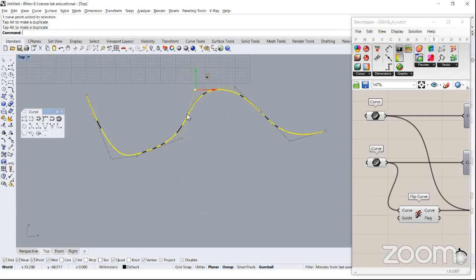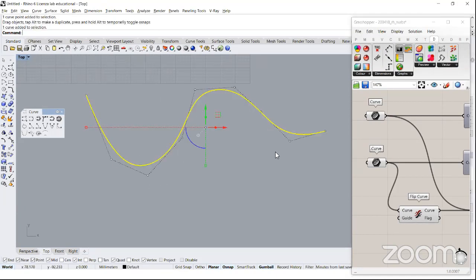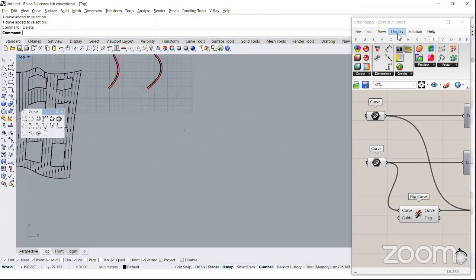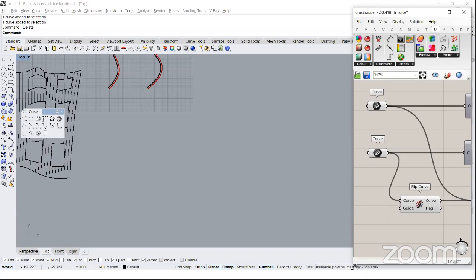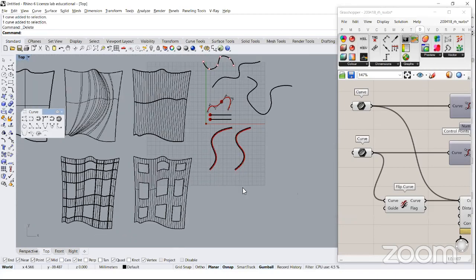So once again, topology, guys, if you know how to deal with topology, you can decide exactly what the shape of the curve is, what part of the curve is deformable and not deformable, and so on. So this that I just showed is the effect of the knot vector. By the way, in Rhino, the best way to control this property is via the control points. But you have to know all the relationships that occur between knot vector, control points, and degree. This is starting to be quite complex, by the way. I'm not going to discuss it further because it really requires a lot of discussion.